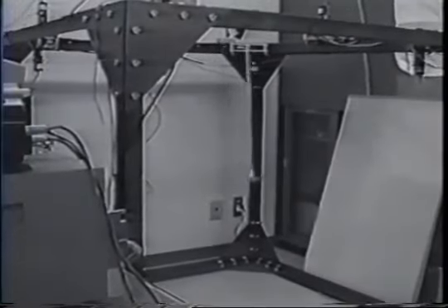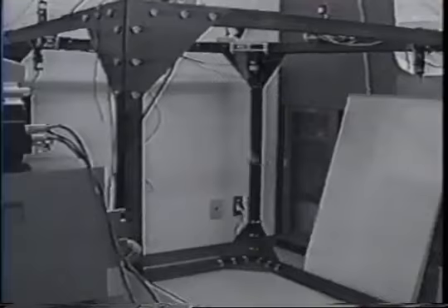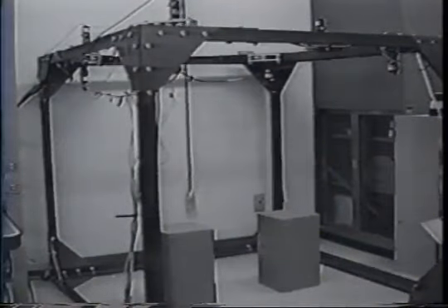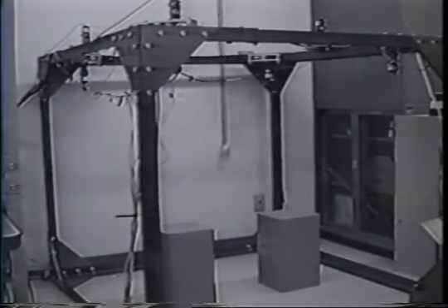The pulleys and gears are made of hard plastic with a gear ratio of 5:1. The rod is made of duralumin and has a length of 1 meter and a mass of 150 grams. Rotary encoders are used to sense the length of each wire. Each DC motor is driven by a simple PD feedback control law on the wire length.